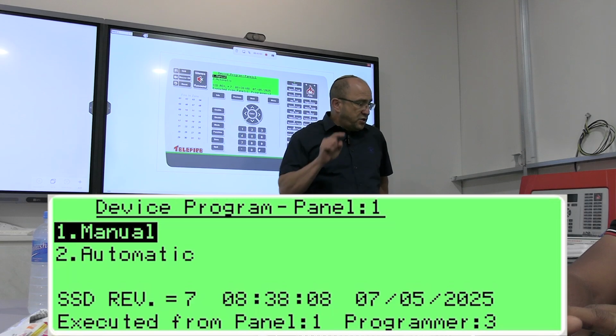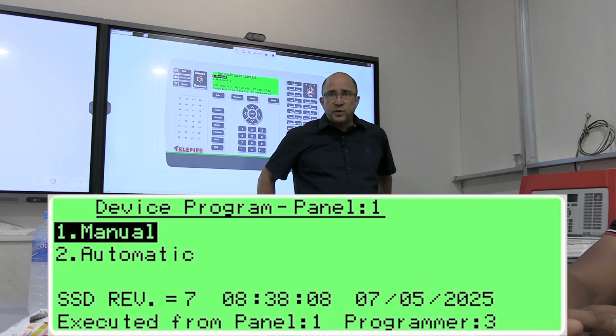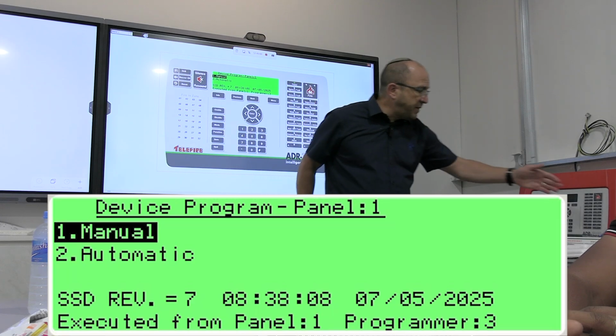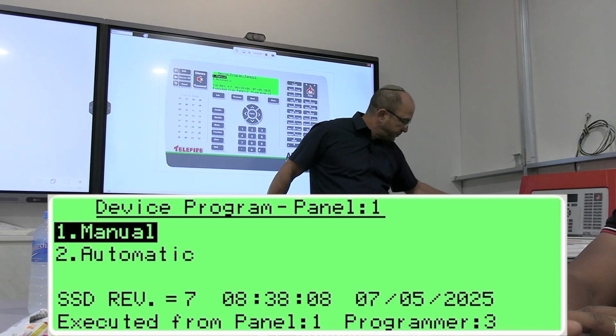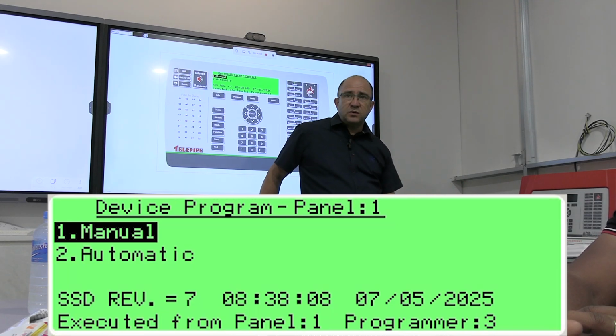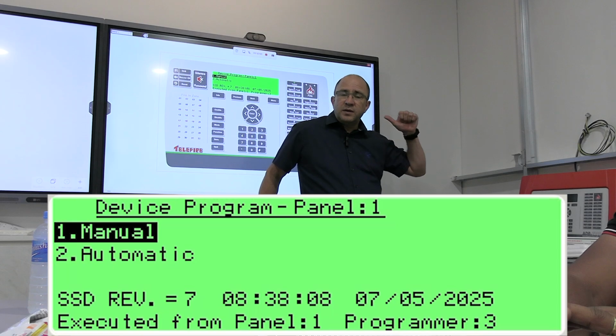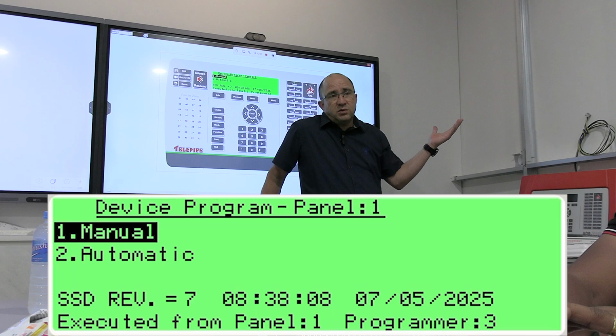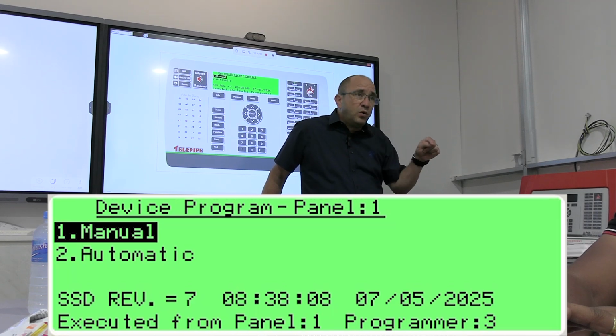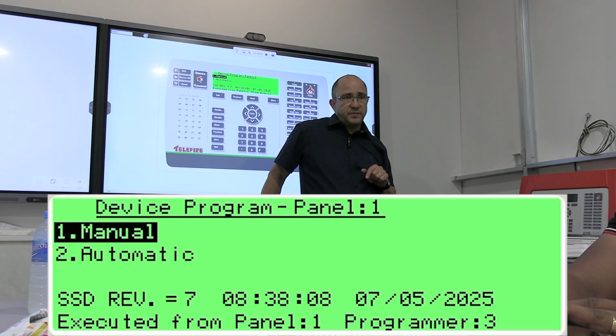Okay? The default of the input switch is an alarm. The input of the red button is an input switch. It doesn't know it's red. The yellow one, it doesn't know it's yellow. It's an input switch. You must go inside this address afterwards and tell the control panel that address number 18 is a switch. We know it's a switch, you don't have to tell me. But the mode of operation is not an alarm. It's a release push button.